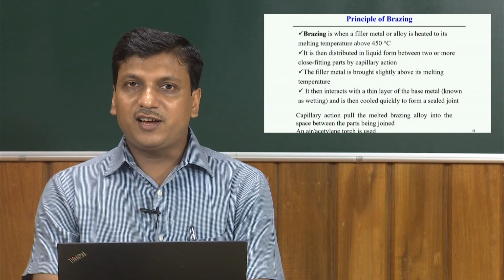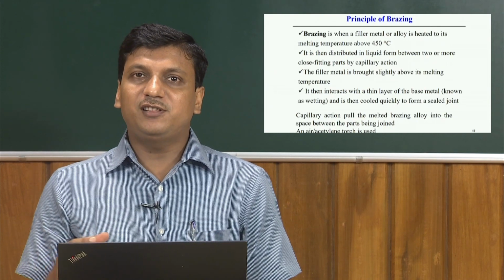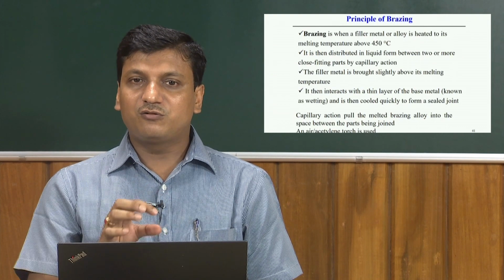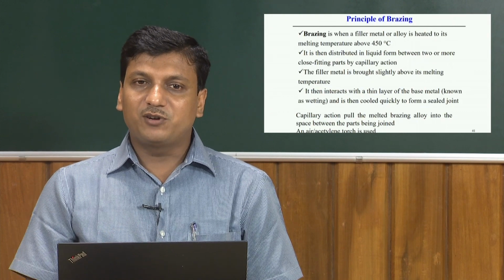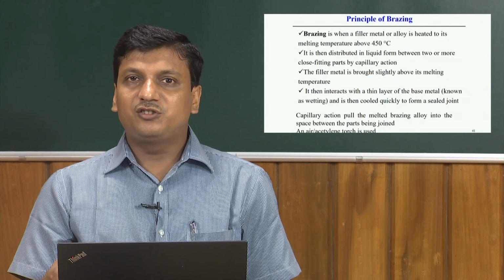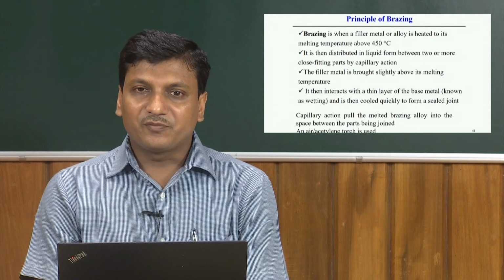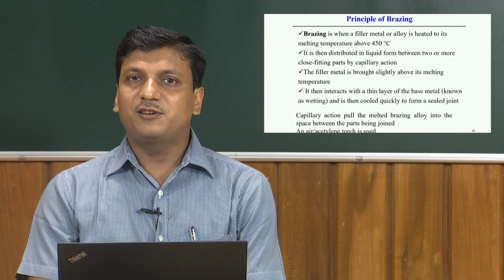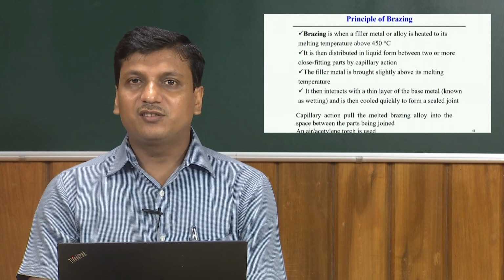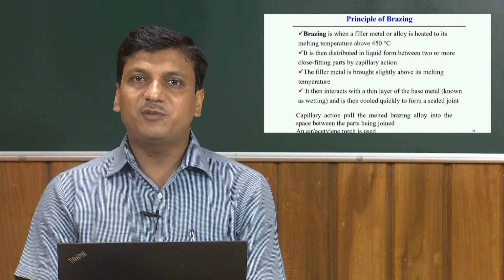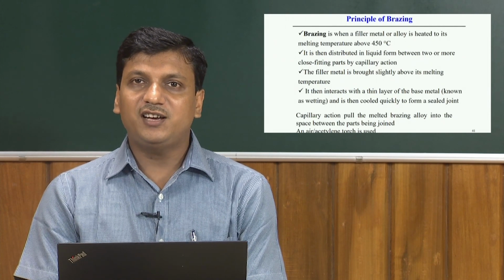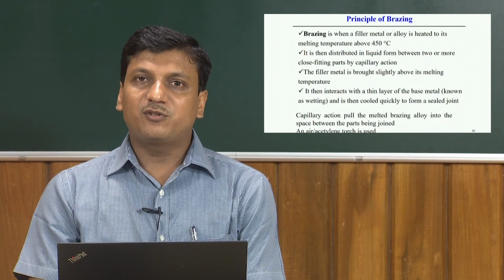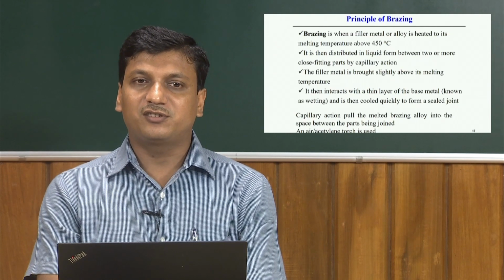Then, after it exactly fills the gap between the two solid metals, after some time it solidifies and cools down to the ambient temperature, and that finally creates the joint between the two base metals. Of course, the intuition is that in this case the liquid metal is simply wetting the solid metal. So, we cannot expect very high strength of this joint like any other fusion welding processes or solid state welding processes.